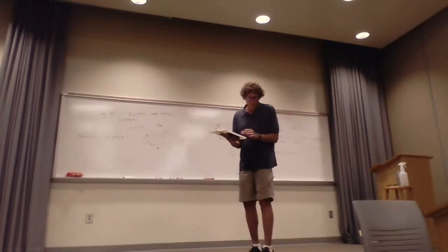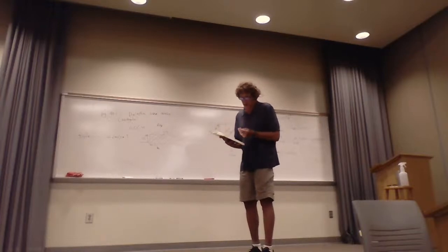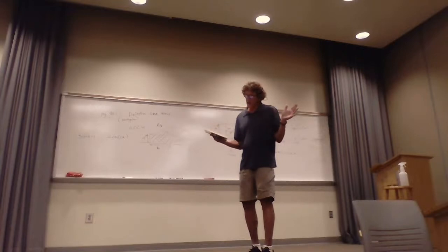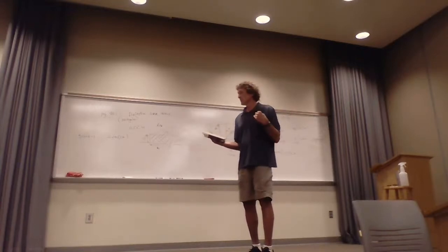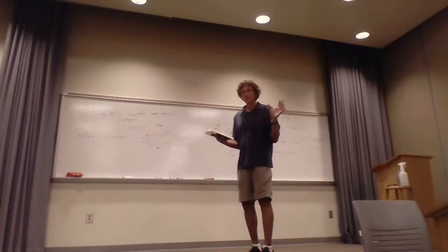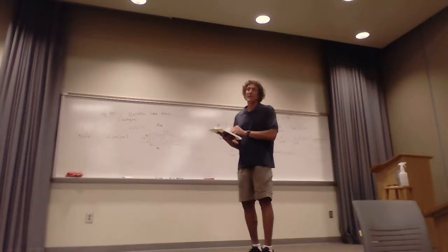It doesn't. So what? We know the frequencies it's going to propagate. It doesn't tell me what frequency I have to be over before I just get one mode. You all follow me on this? Remember with a rectangular conducting waveguide, half wavelength on the base gave you the lowest frequency. You had to be over that frequency to have anything propagate. All right, well, with fiber optics, there is no frequency you have to be over. Y'all hear me on that?